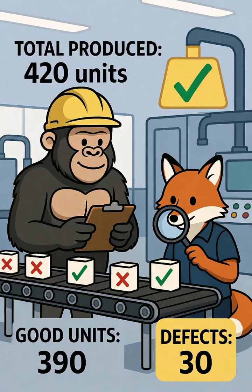Finally, we have quality. Quality measures, of all the parts you produced, how many were actually good. This seems simple, but it includes more than just obvious defects. Quality loss includes fully defective parts that go straight to scrap. Those are total losses. But it also includes parts that need rework. If you made a part and it came out wrong, and now someone has to spend 10 minutes fixing it, that's a quality loss because you consumed time and materials and didn't get a good part the first time.